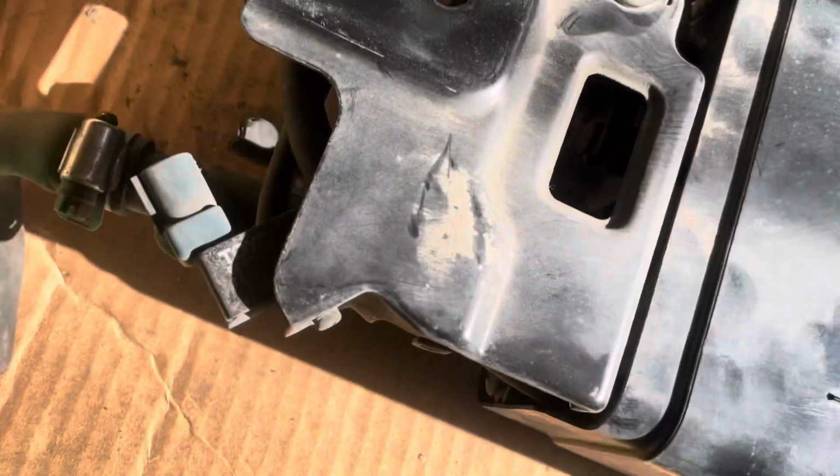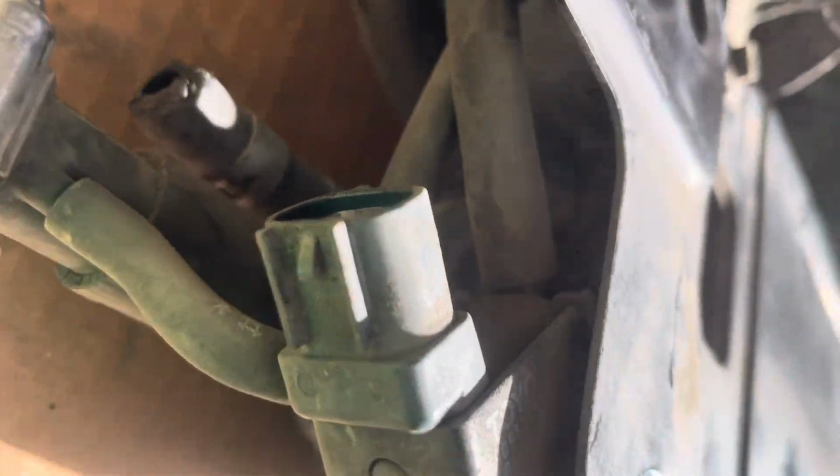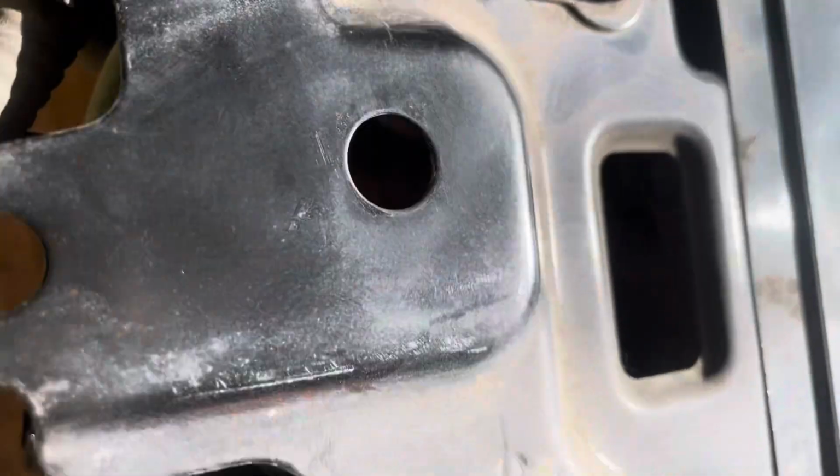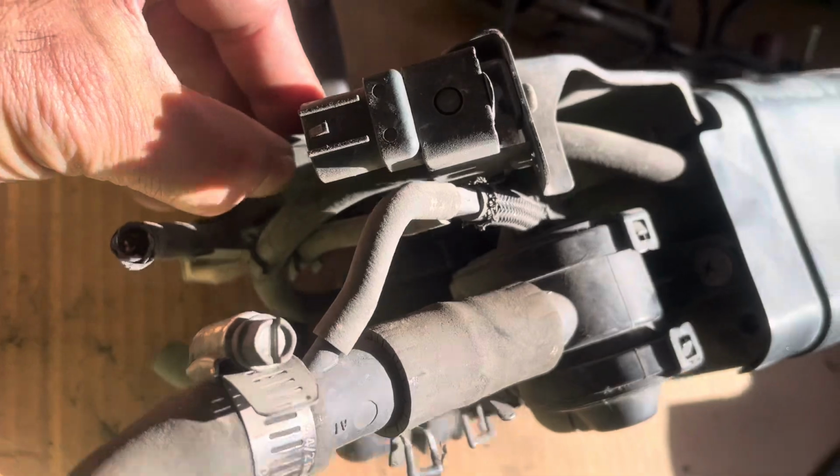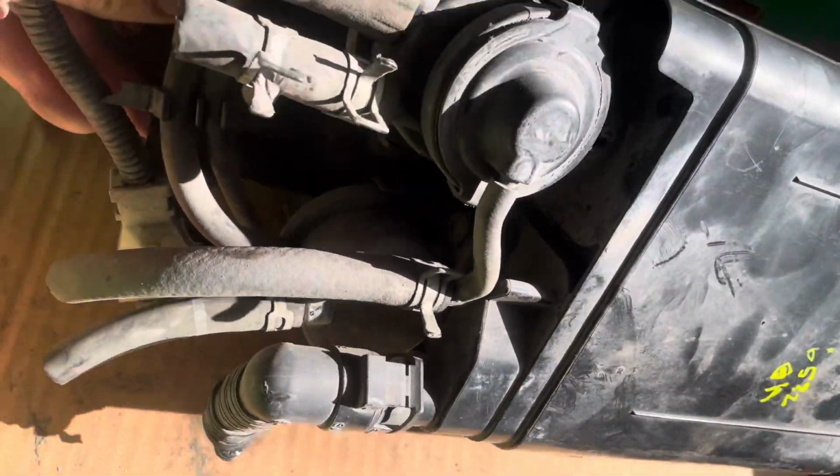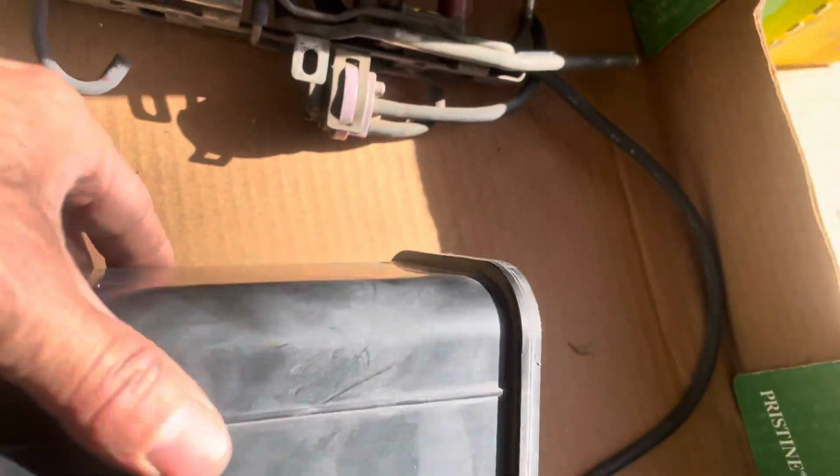And as you can see, the inlet and outlet hoses are 180 degrees apart, so all 3 switches have different hose orientations. The charcoal canister vent is at 90, the evap purge is at 0 degrees, and this one seems to be at like 170 degrees. So maybe that's designed on purpose, or just based on how the vacuum tubes are running.